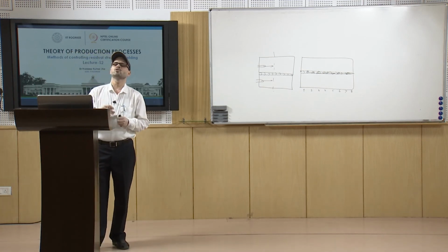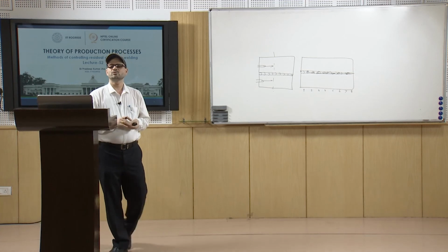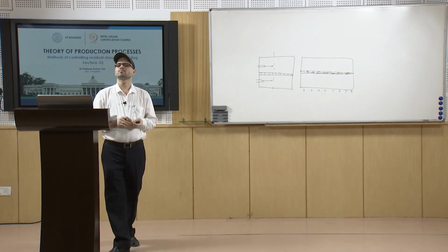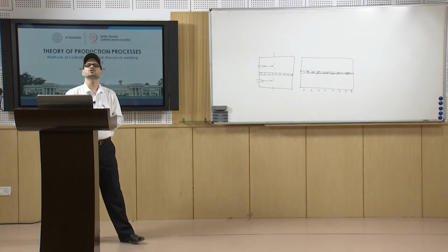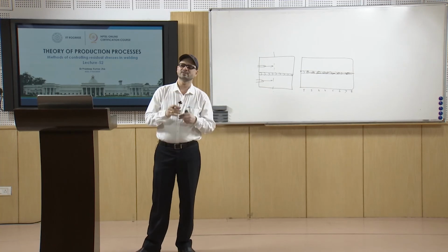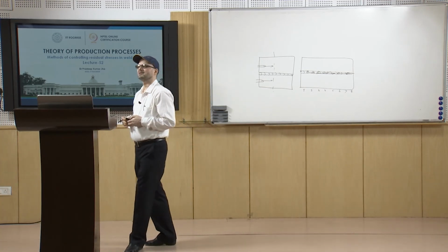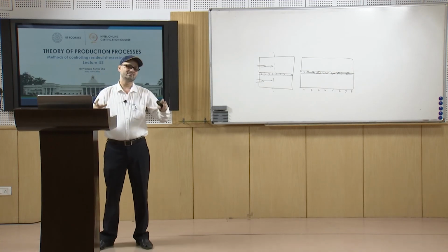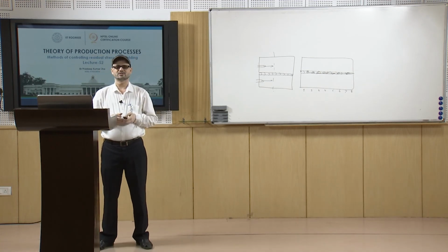Similarly, you can go for fillet weld, which is favorable over the butt weld, and also prefer the provision of structure into sub assemblies. That way there will be more chances of having less residual stresses, and you will have a satisfactory structure.